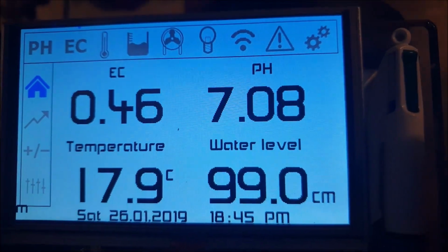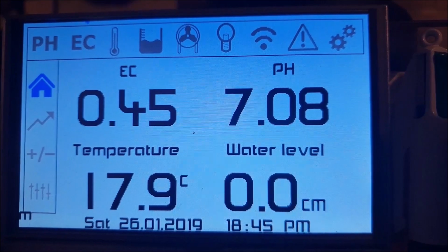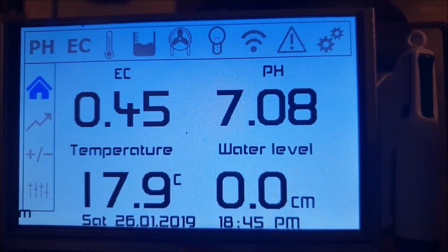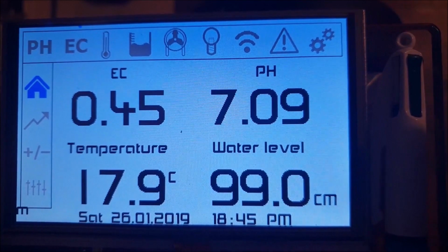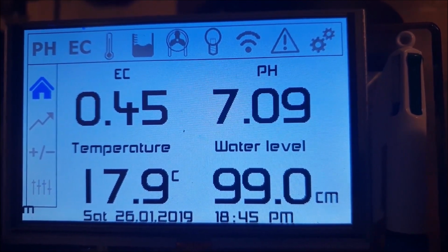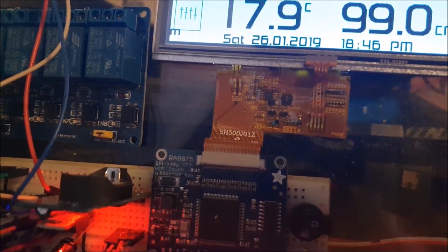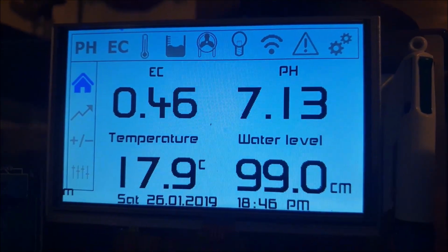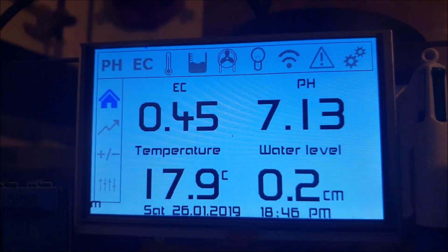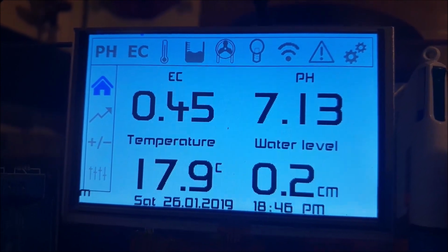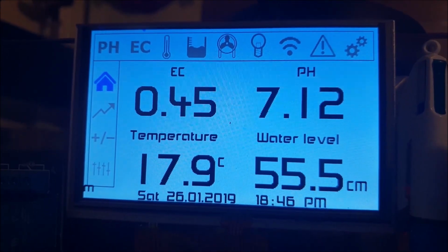Imagine how many, well what is 800 times 480? That's already a big number. And then each one of those is a 565 colour representation, which is hexadecimal, 1, 2, 3, 4, 5, 4, 8, 12, 16, 20. I think, let's say it's 24 bits per colour, per pixel, so 800 times 480 times 24. That's the amount of data required to display that whole display. That is a lot for a poor little Arduino.